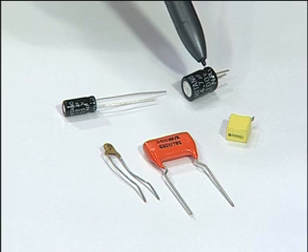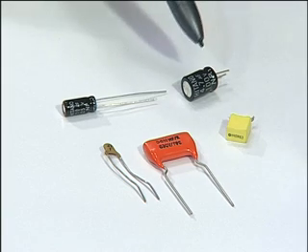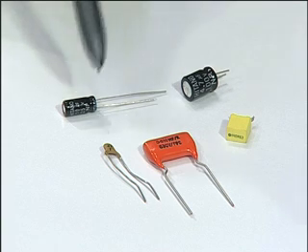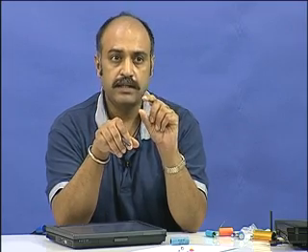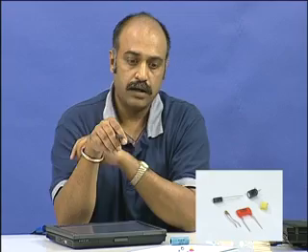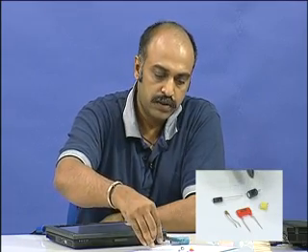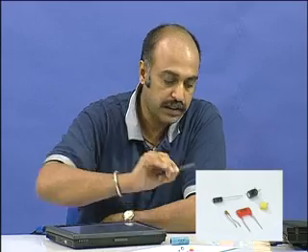This is a slightly higher capacity capacitor, which is as you can see something like 4.7 microfarad written on the body. There is also another value which is written here, 100 volt. On all capacitors, there are two things that you will see on the nameplate. One is the capacitor value in farads or microfarads or nanofarads or picofarads. The second value that you will see on the nameplate is the voltage that it can withstand, because beyond which the dielectric will break down and then it will get damaged. So, you should not apply a voltage to the two terminals which is higher than what is written on the nameplate. Which means that this is a 4.7 microfarad, 100 volt capacitor, and you should not exceed the voltage of 100 volts here.